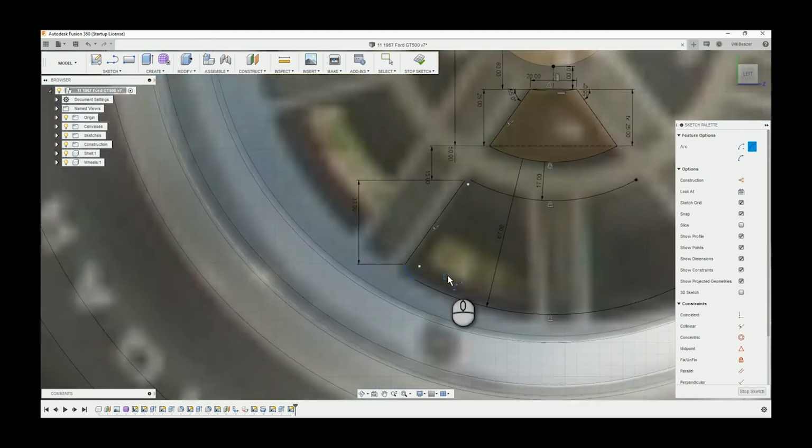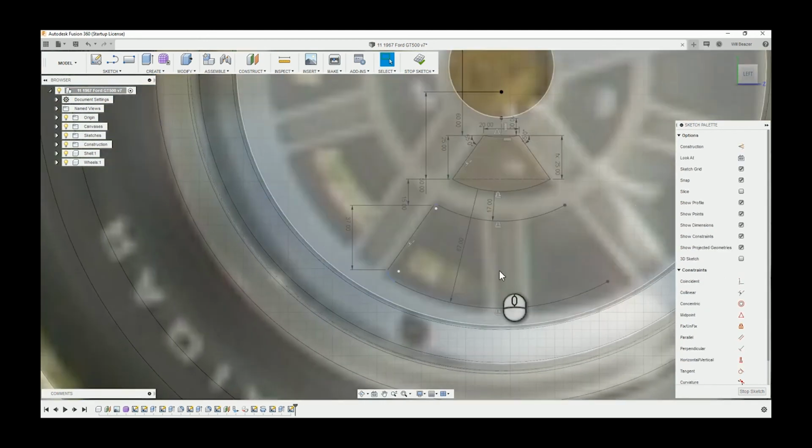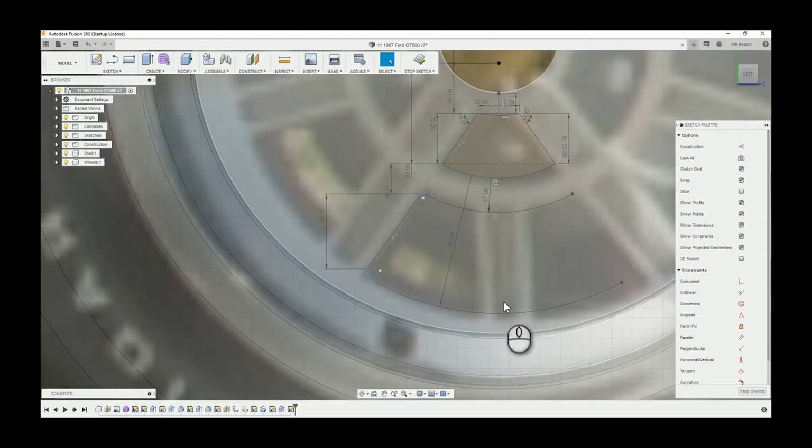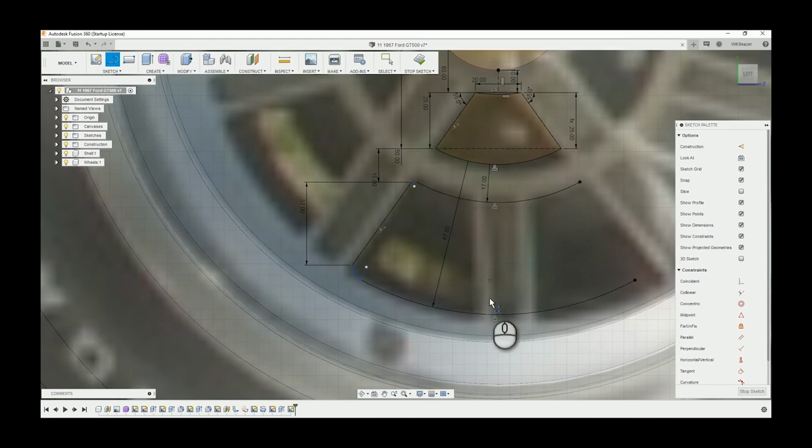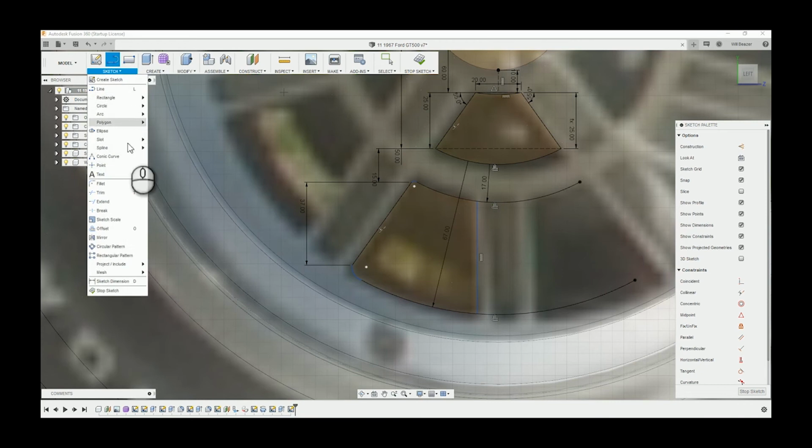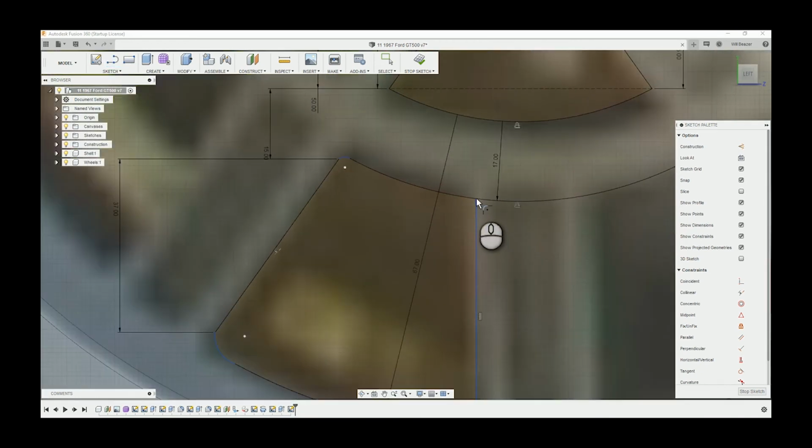So now just sealing these off, drawing a line up from the bottom part up to that section there, and that profile you can now see quite similarly follows the sketch. And then using the fillet tool, I fillet these edges.